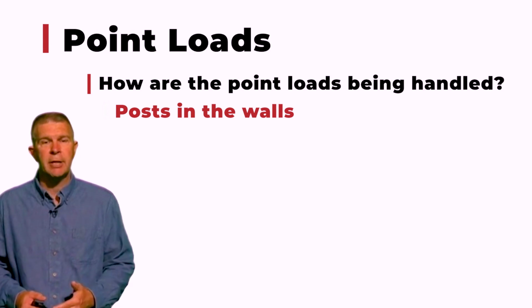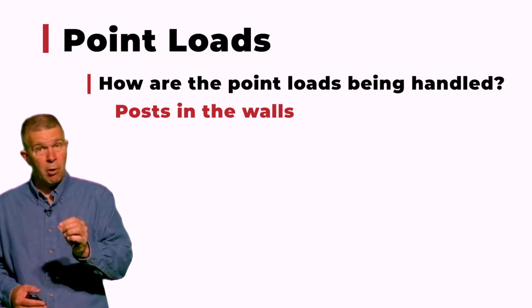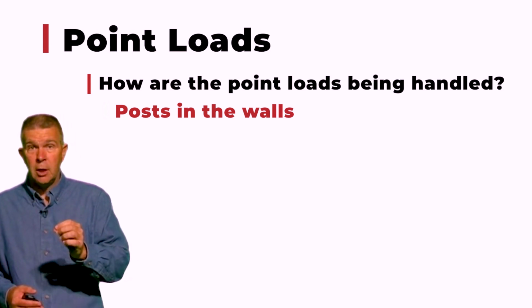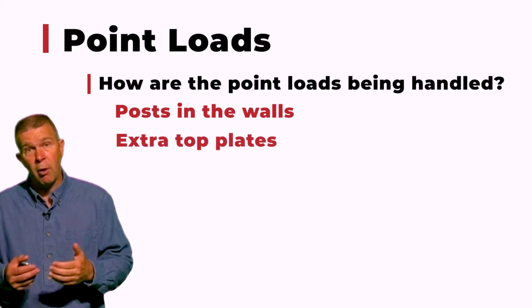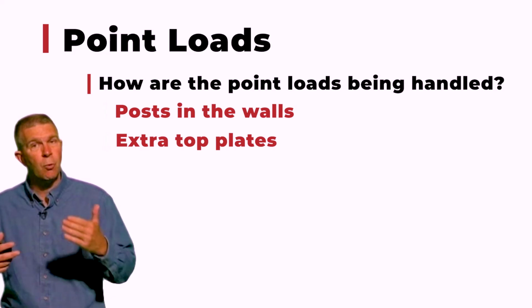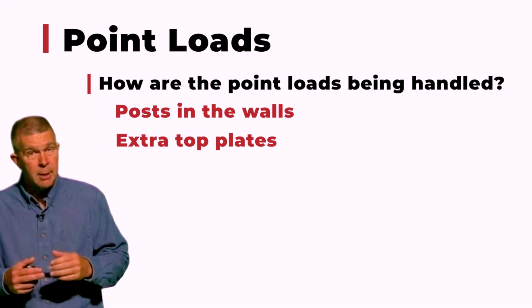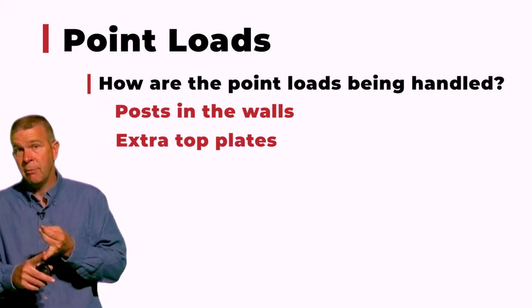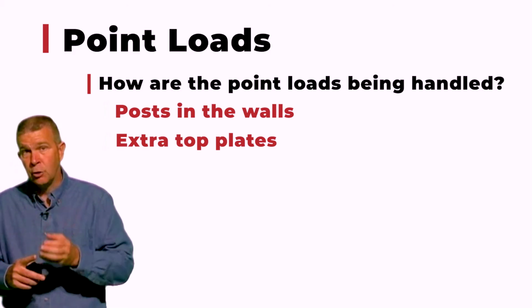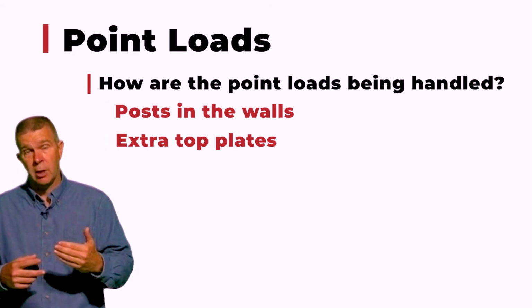system into the foundation. As I said before, when panels are square cut, in some cases, we have the ability to put a shim plate on top of that wall, and we distribute that load so that we don't need to put that post in. By not putting that post in, we save the cost of the post, we save the time of incorporating that post, and again, you, the builder, have the ability to move quicker.